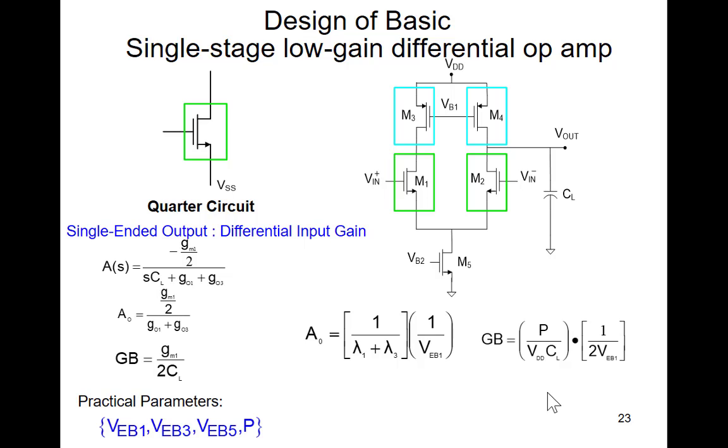It's proportional to your power consumption. Where's the power coming from? VDD. Case closed. Set the gain, that fixes VX's bias. Once VX's bias is fixed, set the power to get the GB. Okay?